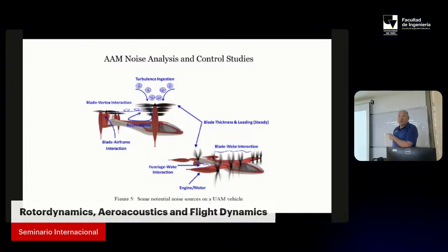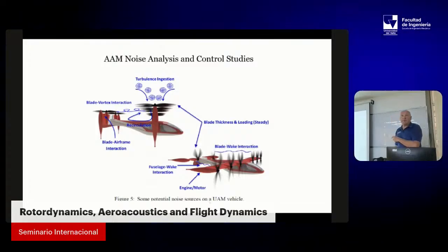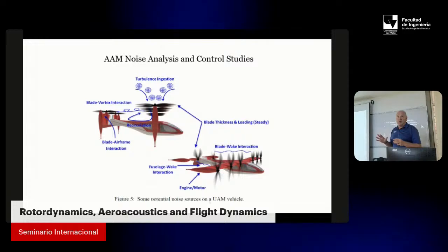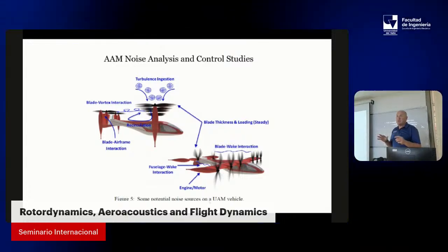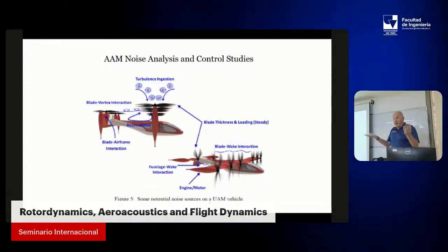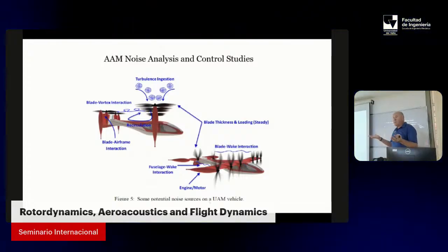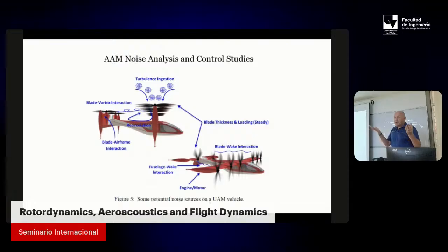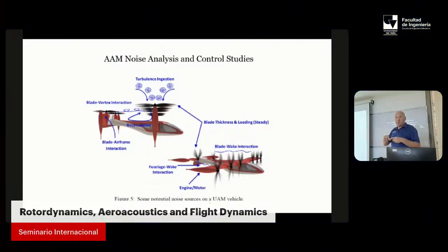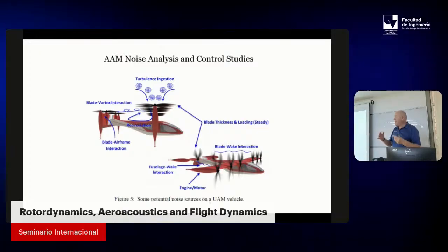And then what these UAM, these new aircraft, like all these eVTOLs, they try to do is distributed propulsion. It's a distributed load system. You have multiple rotors, so this big load is distributed. You have the weight, right? You have to carry the weight. So lift should correspond to the weight, in steady flight, right? So this lift, which is weight, is distributed to many, many rotors, depending on the size and weight, right?